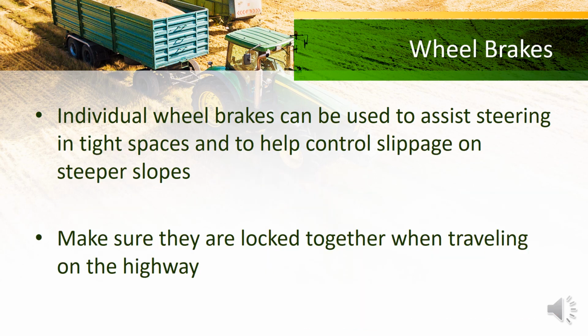The wheel brakes. So the individual wheel brakes are great to use in assisted steering in tight spaces, and they can help you control slippage when you're on the steeper areas. But make sure your wheel brakes are always locked together when you're traveling on the highway.